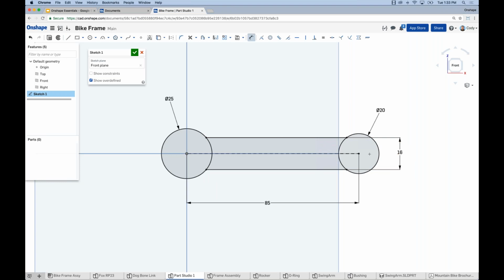And the idea behind that is to let you know that this is a closed shape. You can use it for a feature. So you don't have to go to the feature and then figure out you have some kind of a problem. You can see that right away in Onshape because anything closed automatically shades a darker color than the rest. So it's just one more example of the visual cues that you get that your sketch is good. So we've created 2 circles, 2 lines that join them, about a mirrored line, and we're almost done. The next thing I want to do is add 2 more circles on the inside of these 2 previous circles.